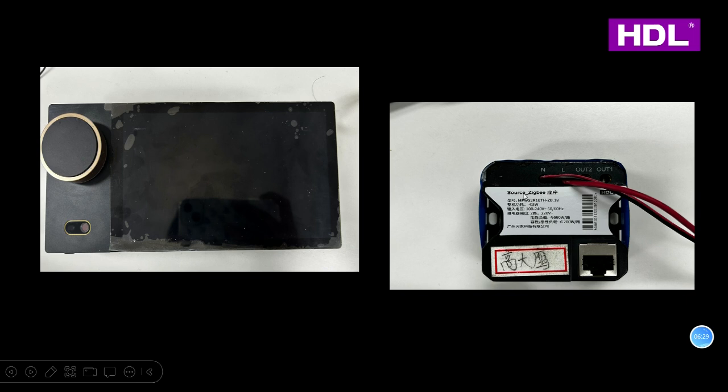You can see here, it's a Zigbee power interface. Then give it power, and the power is 220 volts. Connect it with an Ethernet cable and install the power interface with the panel. Then it can be a Zigbee gateway.